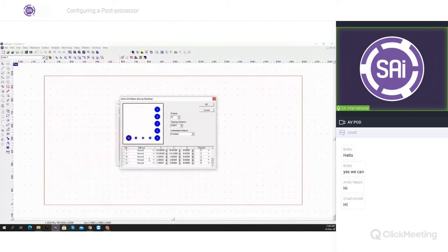And in this case, you can also control the number of drills here. Typically, the distance between the drills is going to be 32 millimeters. For this one, we'll just put this on 160. This one as well.